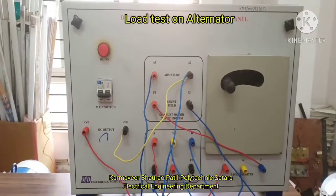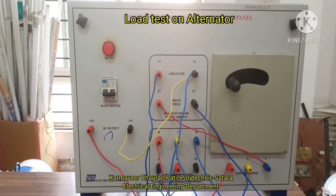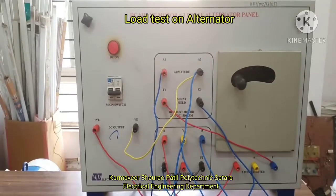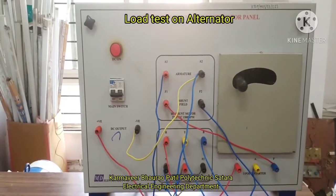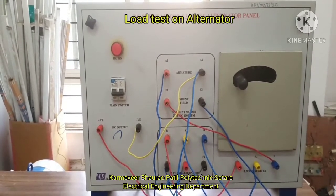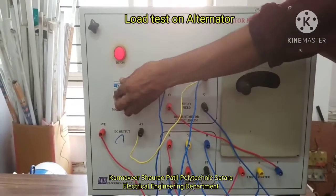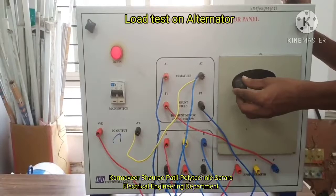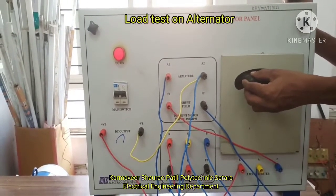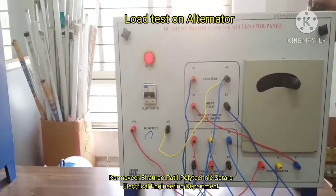So we have completed two setups with resistive load, unity power factor, and inductive load, lagging power factor, and now we are connecting capacitive load, which will have leading power factor. Again a 3-phase load with a star connection, and with this load we will start the machines. First make the motor main supply on, then operate the starter so that the motor will accelerate and reach the rated speed. We have kept the rheostat in a fixed position, so speed is 1500 rpm.